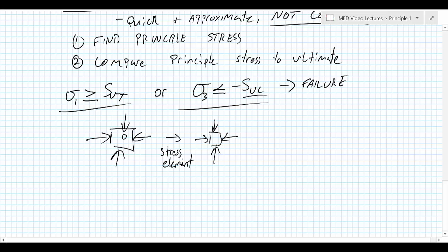So again, loading, stress, failure theory. Every single one of these steps will be exactly the same. And we'll put some complicated loading situation, such that our stress element here has the stress state of 30, let's call it megapascals, negative 14 in shear, and negative 15 in compression in the y direction.